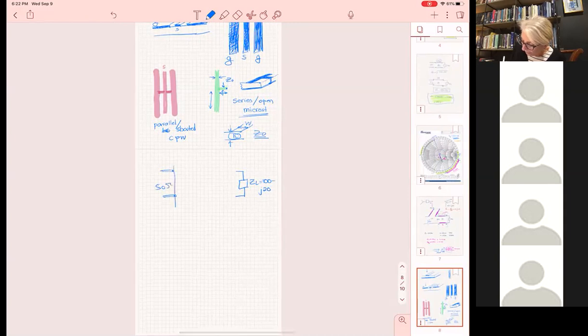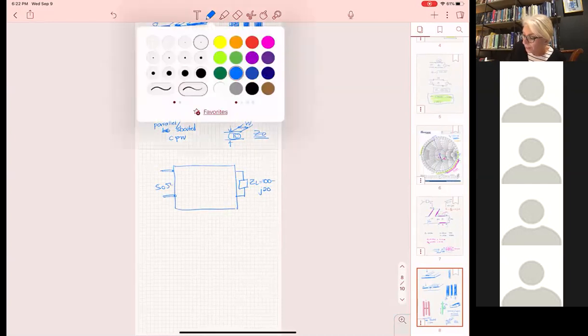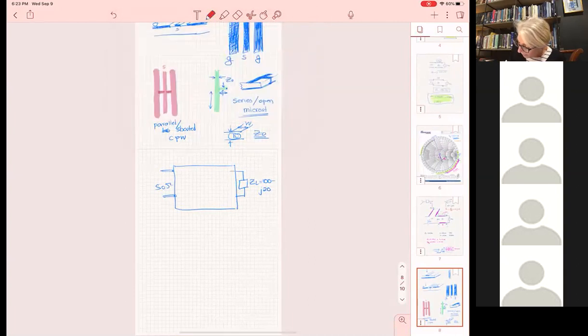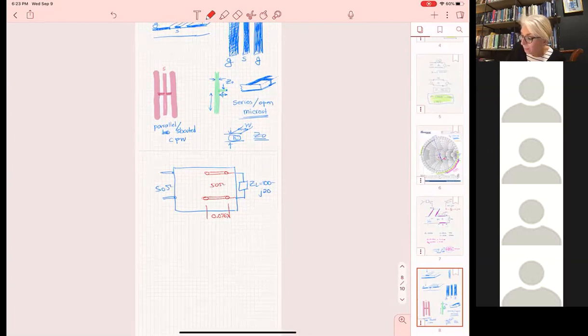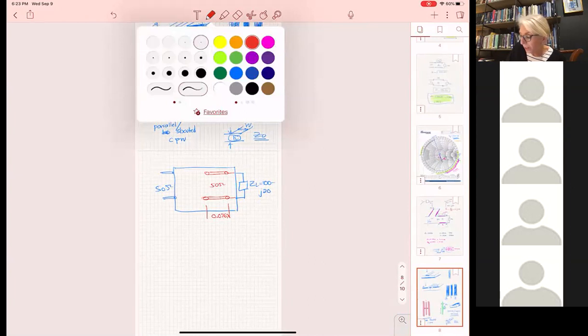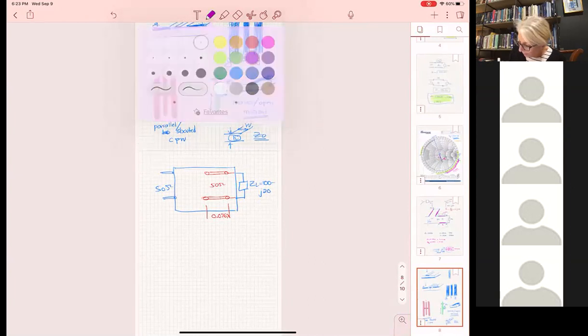And that is your matching network here. And people are telling you that your matching network incorporates the following. It has a section of a 50 ohm line, as we found it, and we found that to be, if I remember, 0.076 lambda. And then we found that it has a series stub, or they give you a series stub.